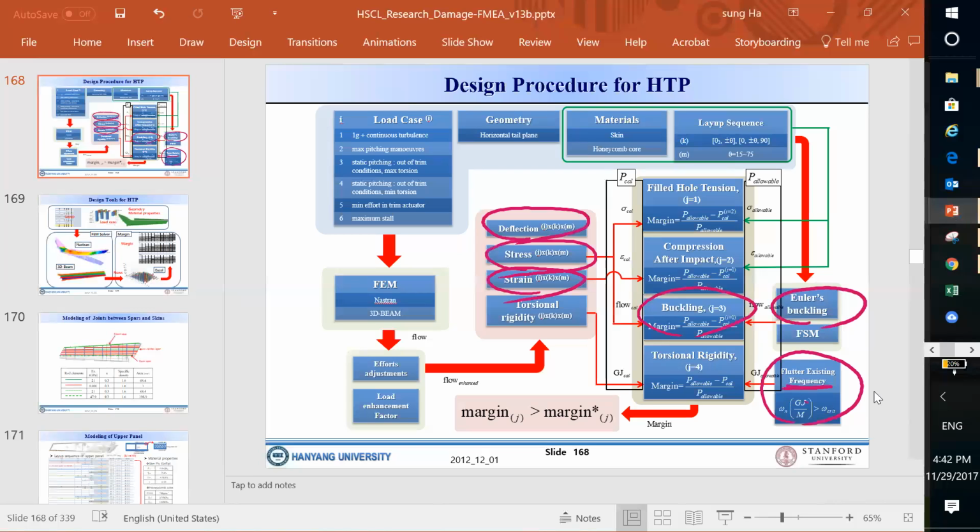So you have to avoid natural frequencies. Avoid this external frequency matching its own frequency. So in the airplane, let's say you have an engine with a certain frequency. If this wing has the same frequency as that, big trouble. The airplane will go crazy, which you don't like.